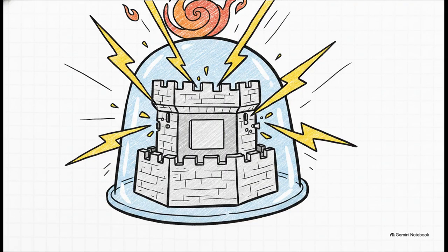And it's not just logic faults or power drops. This chip is a literal fortress against environmental electrical strikes. We're talking massive electrostatic discharge, or ESD protection, absorbing up to a staggering 16 kilovolts for the human body model. Like we mentioned earlier, the bus lines themselves can shrug off extreme fault voltages up to plus or minus 70 volts on those H variants. And hey, if the internal circuitry gets too hot from extreme external temperatures or a continuous short circuit, a thermal shutdown protection kicks in to save the silicon from literally melting itself.